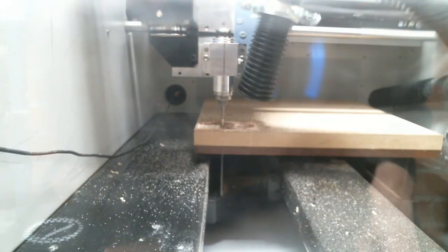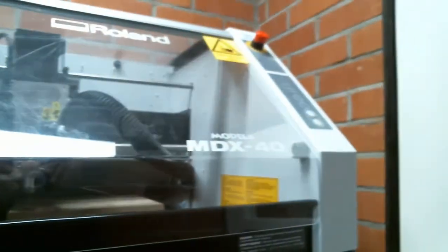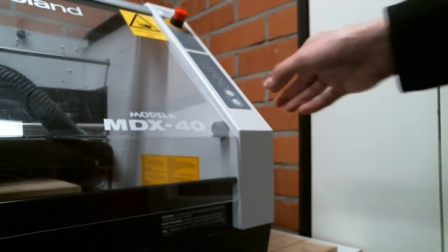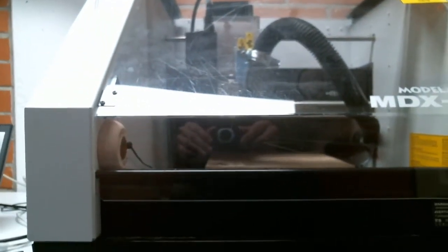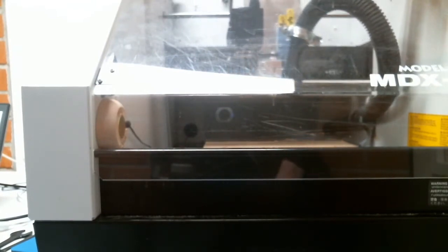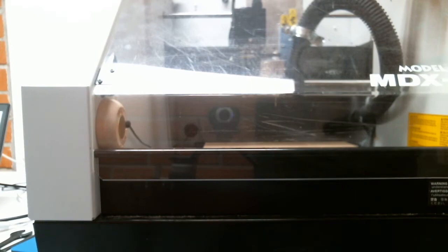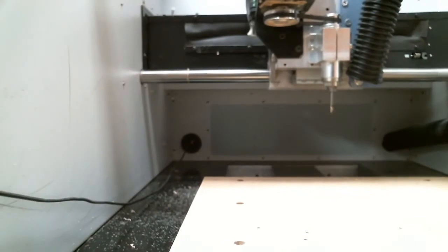Now let's wait till the spindle finishes spinning completely, and it takes approximately 5 seconds for it to slow down completely. Then we zoom out and take a look at this panel over here, and we press the view button. I'm just going to lift the tool, and it's going to move the board forward so we can access it. Once it's done that, we can open this up, zoom in, and hello, there's our board.